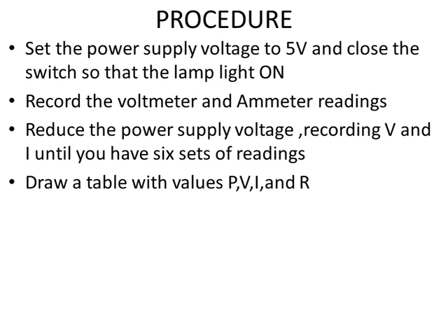So that switch is very important, and you must not just do anyhow with it, or else you will run down your power supply voltage, especially if you are being given a battery. So by the time you close the switch, the light will come on. Then you record whatever you have on your voltmeter and your ammeter.